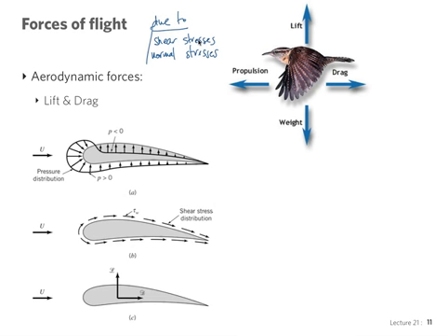So a typical stress distribution would look like this. In the case of the pressure, we might have around a wing or airfoil some distribution of negative pressure, and this was already understood by Sir George Cayley, that you would have a low pressure area on the top of the wing, and a positive pressure in the leading edge and the bottom.